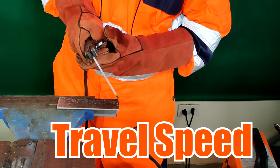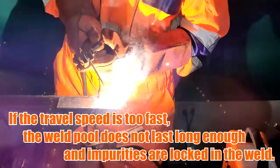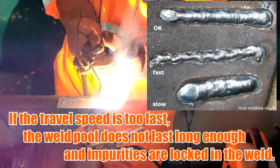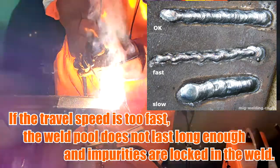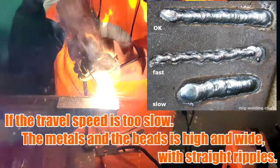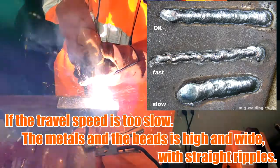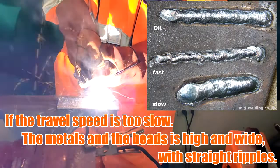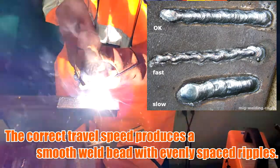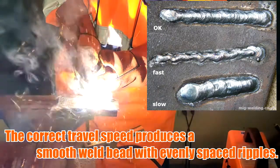Next is travel speed. If the travel speed is too fast, the weld pool does not last long enough and impurities are locked in the weld. The resulting bead is narrow with pointed ripples. If the travel speed is too slow, the metals and the beads are high and wide with straight ripples. And if the travel speed is correct, it produces a small weld bead with evenly spaced ripples.